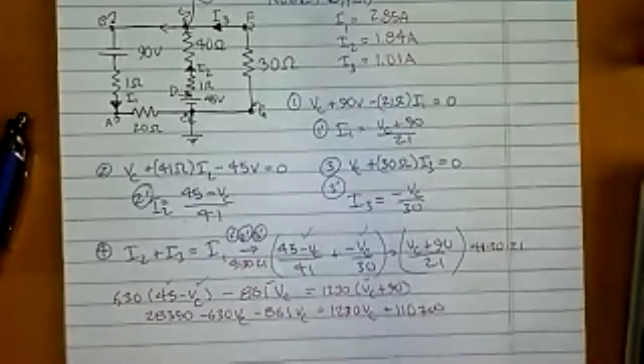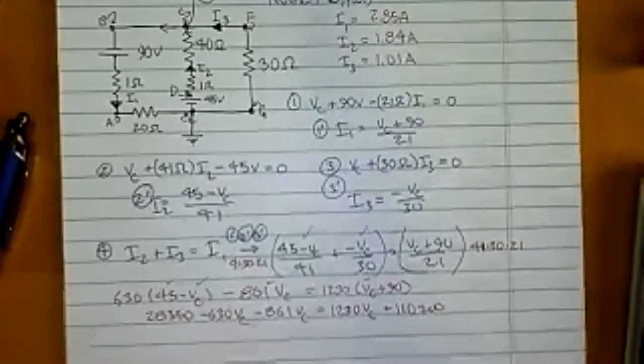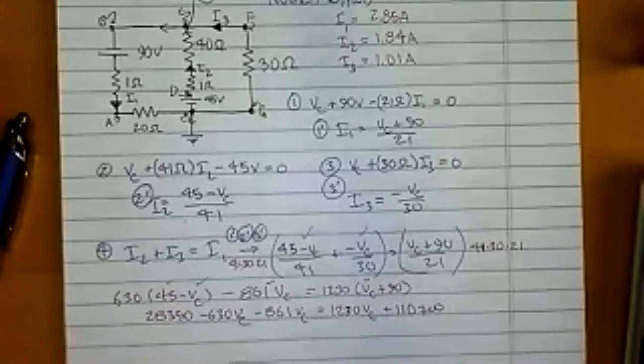Notice this equation. This is the whole beauty of the nodal method. By having each node only have two unknowns, the VC and then the current for that one, we automatically get a really easy system to solve for VC. Once we have VC, we go back and plug that into the individual currents, and that gives us our currents. And the benefit is we get the voltage at a particular spot too that we didn't necessarily ask for.